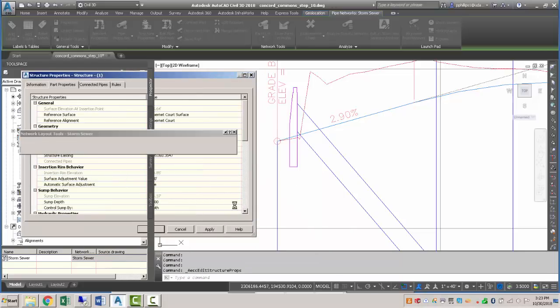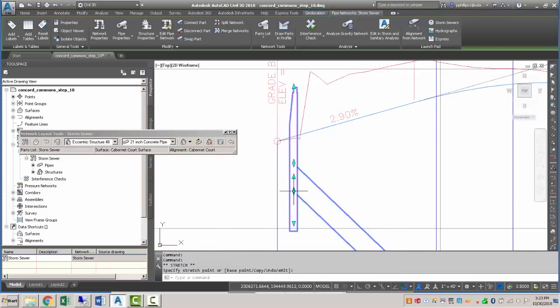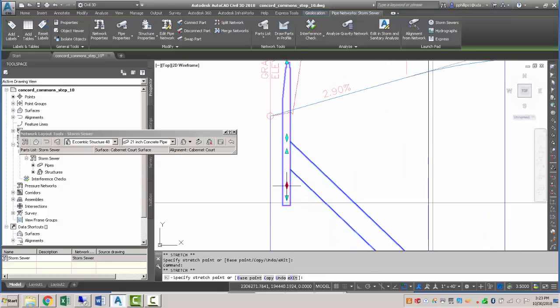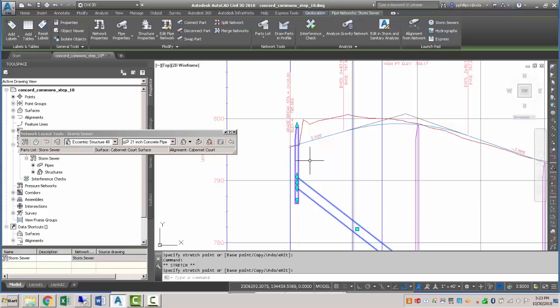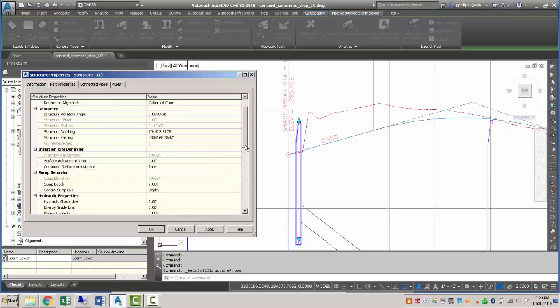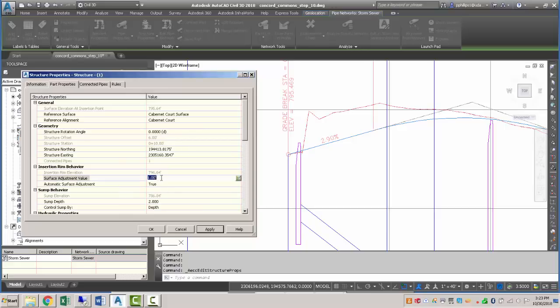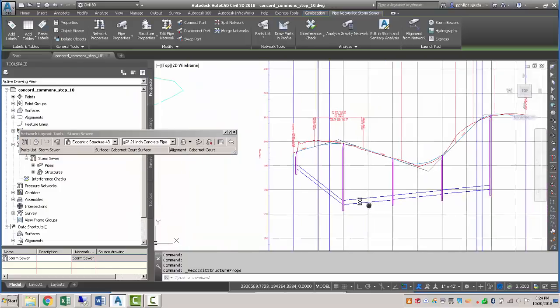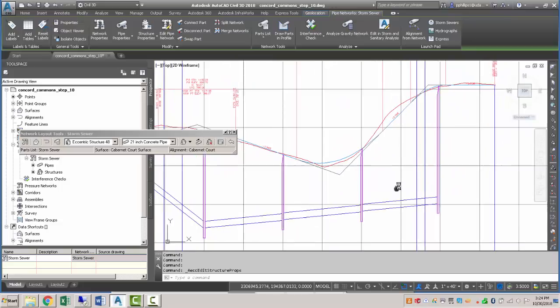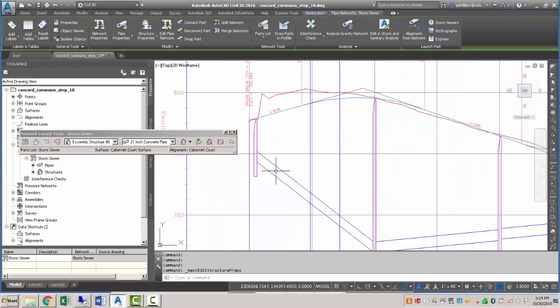And the problem is that this pipe probably is too high, so let's lower that. We can just use our control points there, and then let's try to move the top of this pipe back, or top of this manhole cover again. So I'll change it to 1 foot, just see if it actually applies. Looks like it worked. And then let's reset it back to 0 to bring that top of manhole cover to the right spot. You can see we've got an appropriate slope here of probably 1%, and then this pipe's actually going the wrong direction. So we're going to need to bring that down,